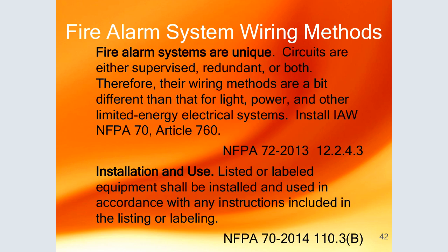So, fire alarm system wiring methods. We have wiring methods for the fire alarm system, and fire alarm systems are unique. Circuits are either supervised, redundant, or both. Therefore, their wiring methods are a bit different than that of light and power and other limited energy electrical systems.